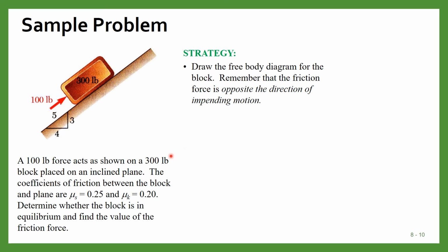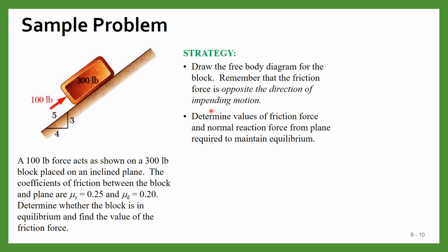First we will draw the free body diagram. Remember that the friction force is opposite to the direction of impending motion. So in whichever direction you know that the block will move, you will apply the frictional force in the opposite direction.